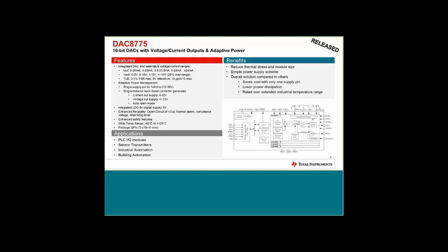In addition to those features, the device is smart, if you will, and can be programmed to automatically go into a fail-safe state if one of these conditions is reached. And by fail-safe, we mean you could switch off the DC-DC converters and power off the current output such that you're in a zero output state and there are no high voltages present from the DC-DC as well. Altogether, this goes into a 10 by 10 millimeter QFN, which again is helping us realize our size goals.